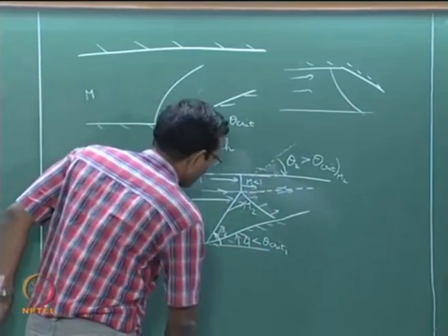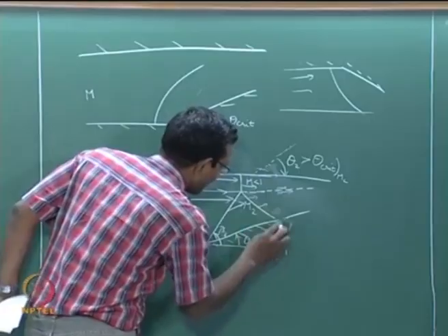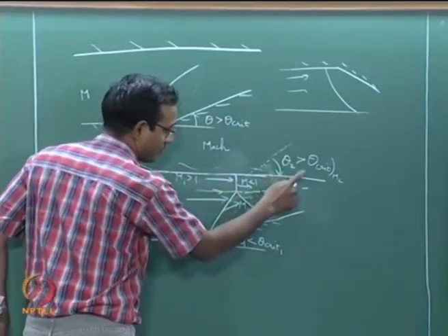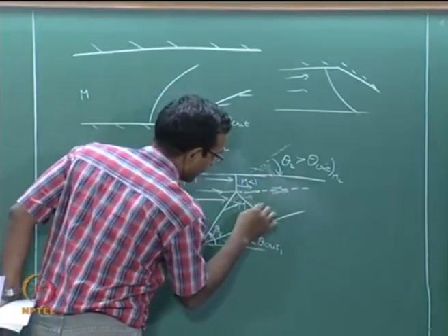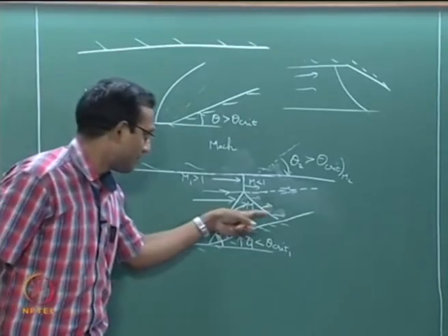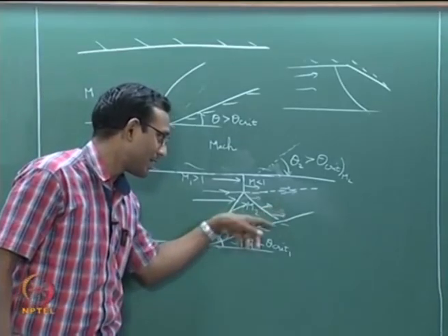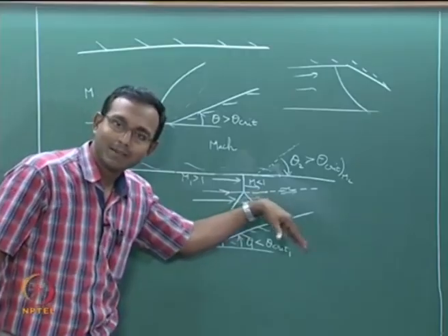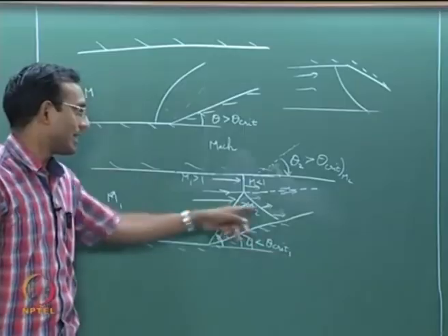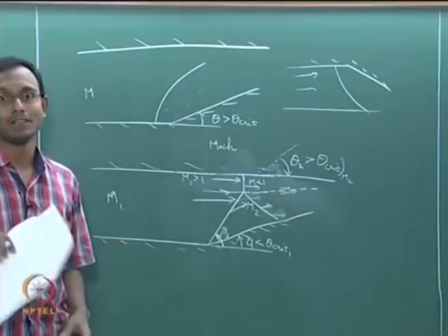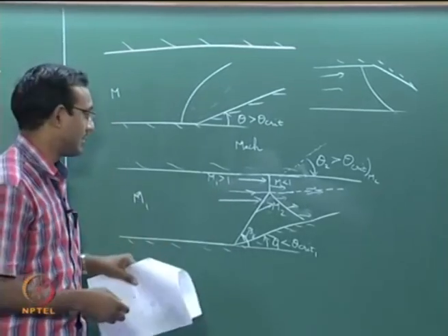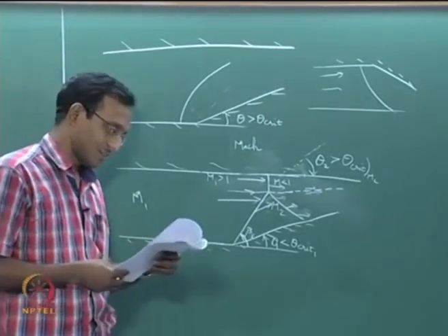Oh, I drew this final angle wrong, it should still be parallel to the top wall because this reflection is coming from this wall, it is going to be close to that, but it may be slightly tilted. And now this streamline will go and interact with this bottom wall and it will again bounce off from here because it is seeing a wall going through the streamline. So, it will again bounce off one more round, that is a possibility. If there is viscosity, these things will not happen this well, there will be a more difficult thing to solve.